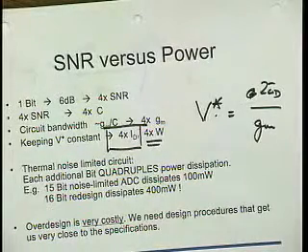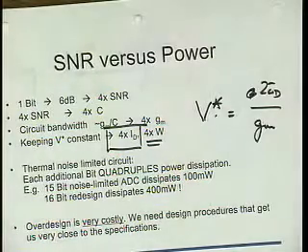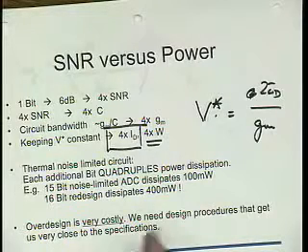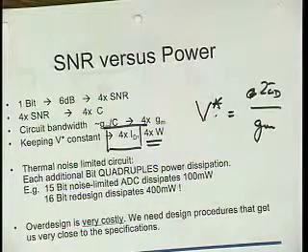To put this into perspective, let's suppose that you've designed a 15-bit A to D converter, and the marketing guy comes around and says, this is wonderful what you did, and it dissipates only 100 milliwatts, that's so wonderful. My customer really just wants one additional bit, and I'm going to sell 10 million to him. And the power, 100 milliwatts is just fine. And you tell him, sorry, but now the power is going to be larger, about 400 milliwatts. The salesman probably is not going to have a very good day, but this is physics. Too bad. Over-design is extremely costly.